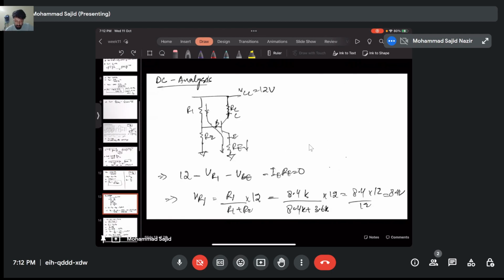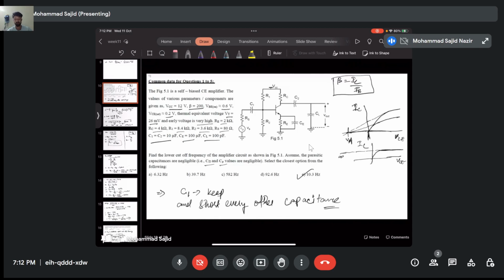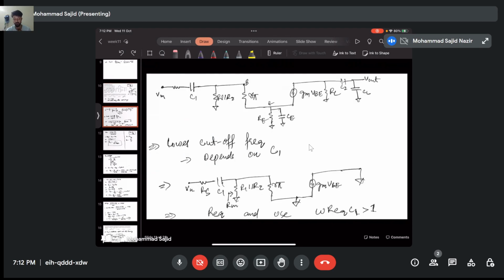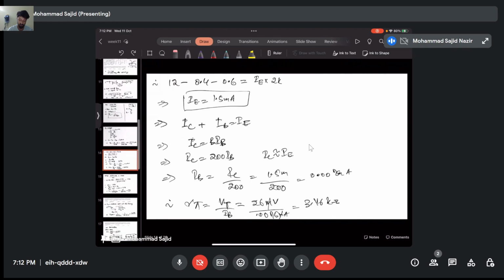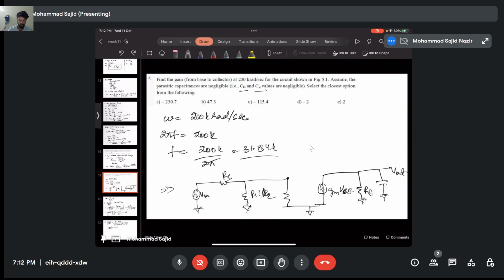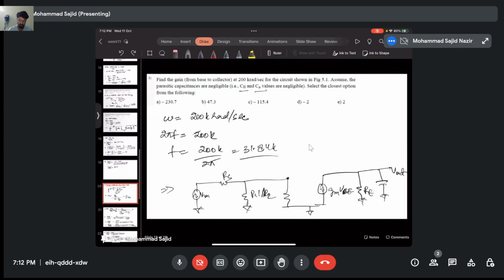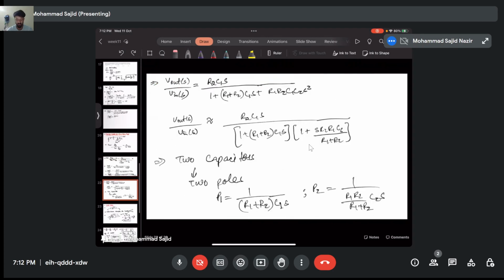And this question gave you a slight bit of introduction to the BJT. Try to get these relations like gm, r pi from your end as well. Okay, so basic BJT formulation like IE is IC plus IB, IC is beta times IB, and similarly alpha. You can use those. Those are very basic to BJT. Then this is first the frequency response, just to check how you can calculate the poles in the circuit. Okay, go through it.